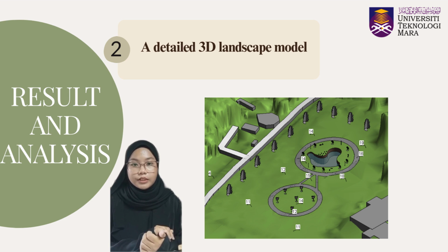The lowest elevation, which is 4 meters, is located in the southwestern area, while the highest elevation, 19 meters, is in the northeastern area. The elevation gradually increases from the southwest toward the central and northern parts of the site. The landscape features are strategically placed according to the site's elevation and terrain characteristics. The open green space, which is between 11 and 40 meters, promotes effective drainage while maintaining visual appeal. And the higher elevation, which is 18 meters to 19 meters, functions as natural drainage divides, directing surface runoff away